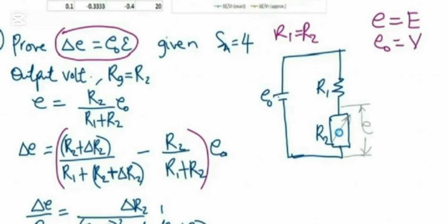But as I said earlier, we use the principle that change in resistance over initial resistance is proportional to what? To strain, where we have a sensitivity. So the strain gauge is like a transducer. It doesn't measure strain directly, but you use it like a converter, to convert from one quantity to another. So in actual sense, when you use the strain gauge for a variety of loadings, what you are going to get is change in resistance of the strain gauge, which you then convert to what?